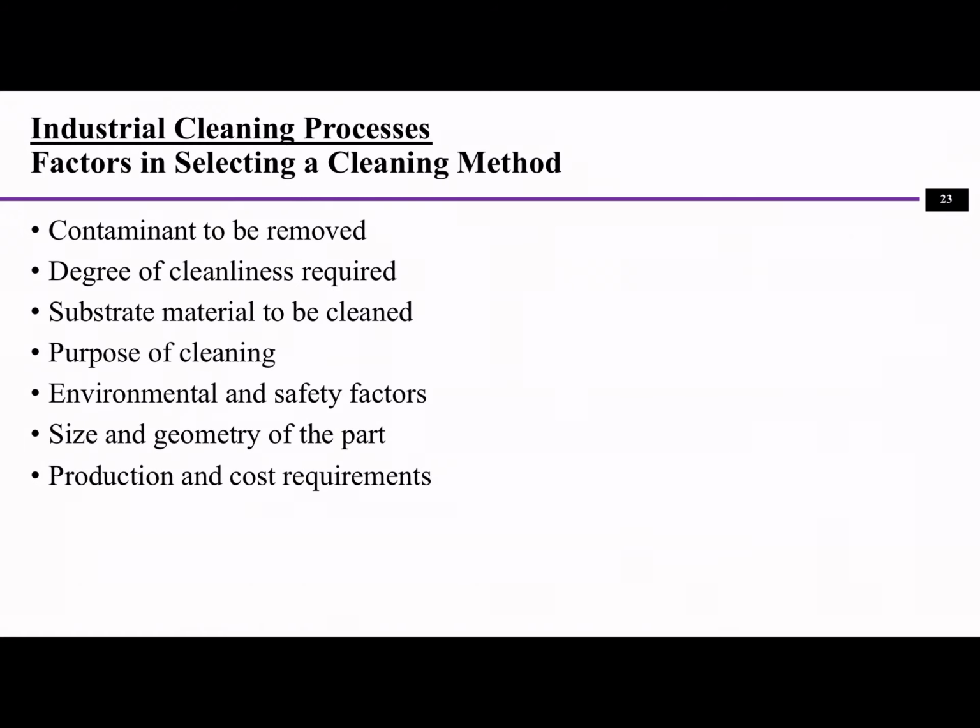And when we are choosing a cleaning method for the surface, there are several factors we need to consider. For example, what kind of contaminant needs to be removed, and what degree of cleanliness is needed, right? And also what kind of substrate material you are dealing with, and what the purpose of the cleaning is. Some environmental and safety factors, also chemical versus mechanical.